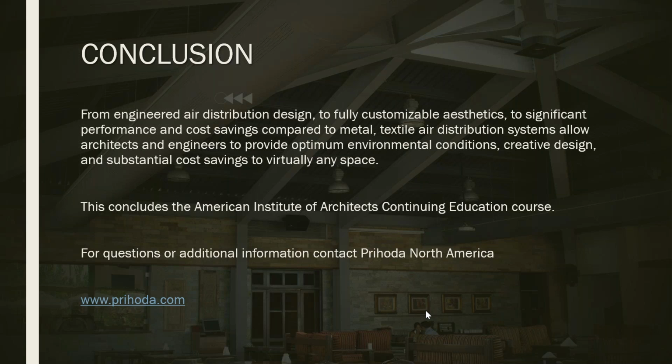Does that change for especially long fabric ducts versus short ones? No, because again, it works off of static regain. By the time the air hits the end cap, the pressure is going to regain in the duct. Where you're going to have your pressure loss points is if you have any fittings or offsets.